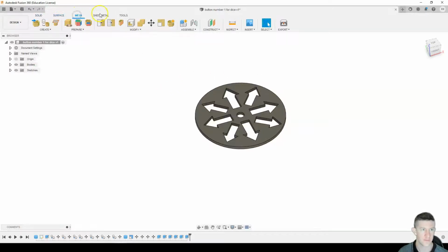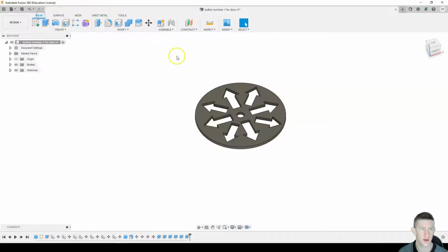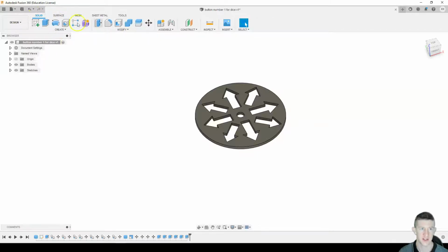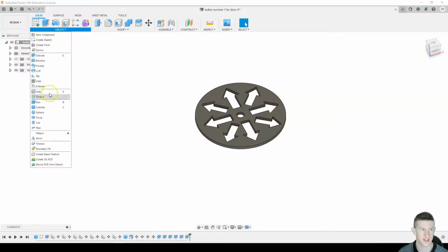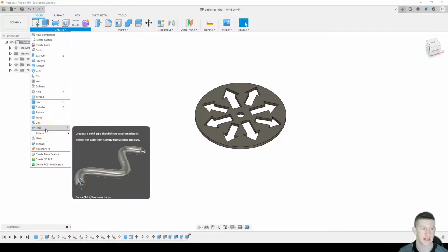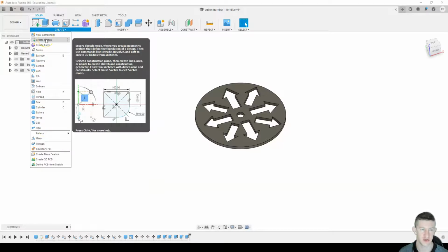These settings across the top are a little bit more complex. Generally what we will work with is in the solid section. That's sort of just creating models and things like that. There are tools to view it in a 3D mode with different lighting. Meshes is more about if you import an image, often it'll import it as a mesh, and we can look at how we convert it back into the solid thing, which sometimes they call a B-rep, but we'll deal with that later. So in general, you've got your create, which is building things from scratch, and you've got all of your options here. The most common are boxes, cylinders, spheres, a torus, coils, pipes, things like that. We can also create sketches, which is basically drawing a two-dimensional image, and then we can make it three-dimensional later.